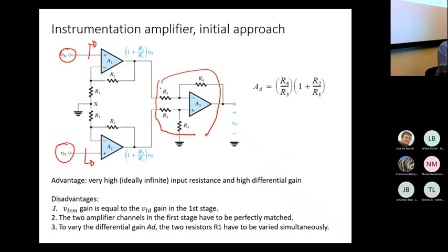Second effect is that since we have this non-inverting configuration, which is an amplifying configuration, we have an additional amplification step to be used for the global differential gain setting. So the differential gain in this new configuration is not just limited to the gain of the difference amplifier, which in this case is R4 over R3, but we have this additional term which can be very useful.